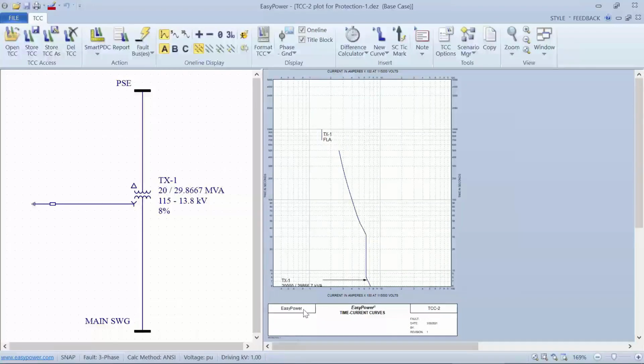If you look down here on the indicator bar, my cursor on that full load current is 150 amps at 865 seconds. So that's the full load current. And so no matter what I do, that's the maximum current that the load should ever achieve.